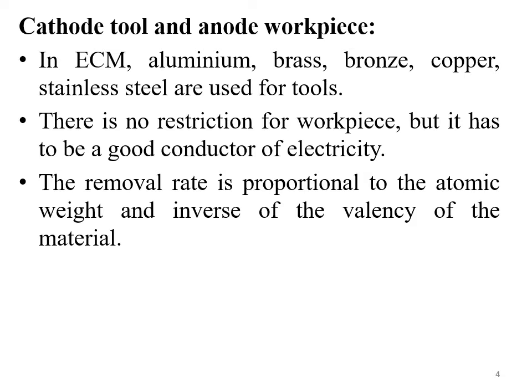Whether it is a very hard material or a soft material is not an important criterion here, because the material is removed by the separation of metal ions due to the electrolysis phenomenon. The only criterion is whether, through the electrolysis process, the metal ions are able to dissolve into the electrolyte solution or not.